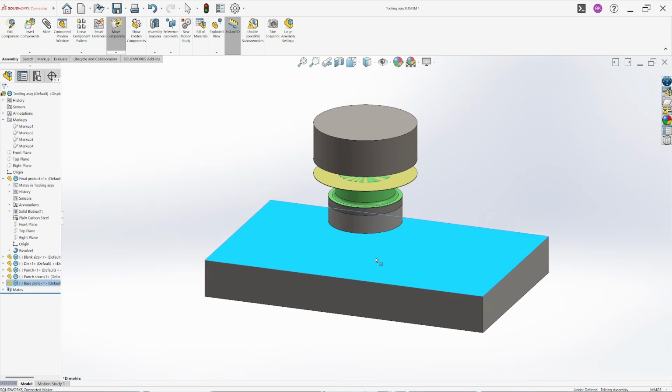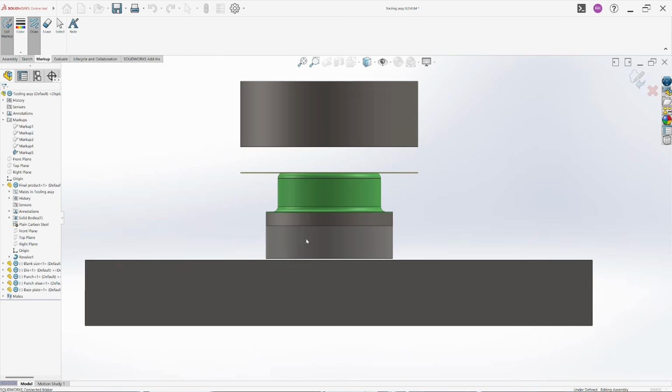Now how can we mount our base plate with this spacer? Here we not just have to mount it, but also position it with the base plate. For positioning, I would like to use a dowel pin right here. For mounting, we have two options. The first option is to make a threaded hole in the spacer, at least 2 or 4 holes, and use bolting from the bottom of this plate. There will be a long bolt which will be tightened into the spacer. And believe me, this is not a good idea.